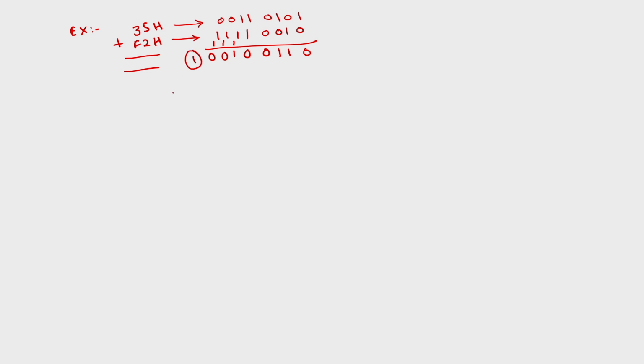So, there is a carry out of the MSB bit. So, the result is greater than 8 bits. This implies the carry flag will be set.